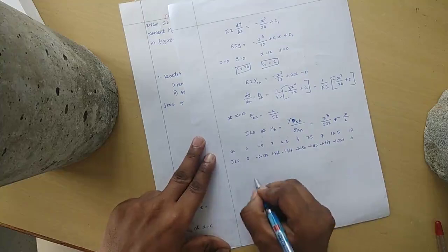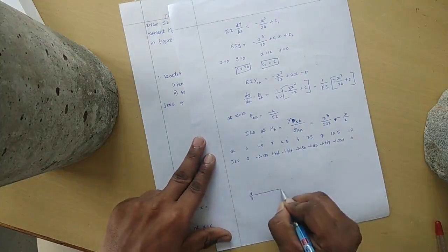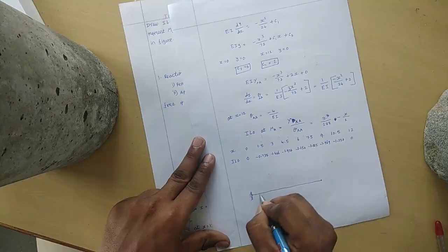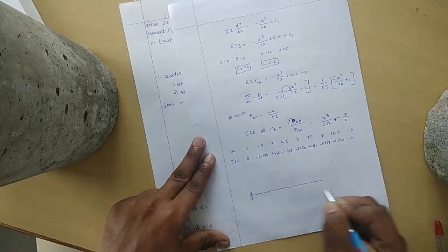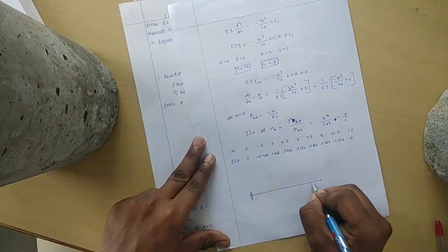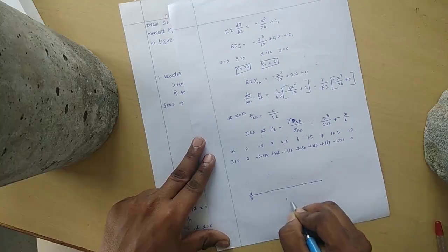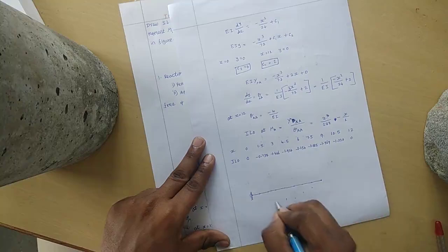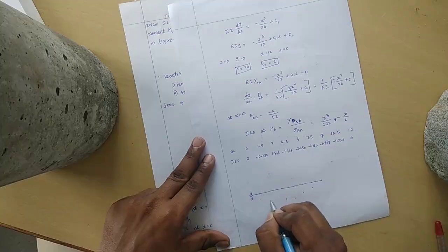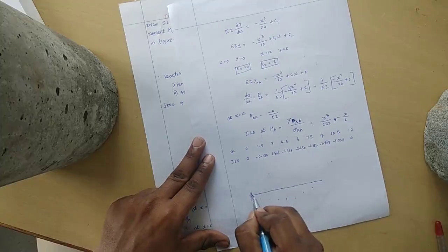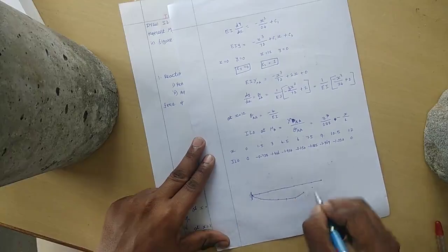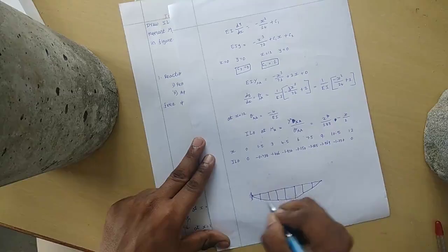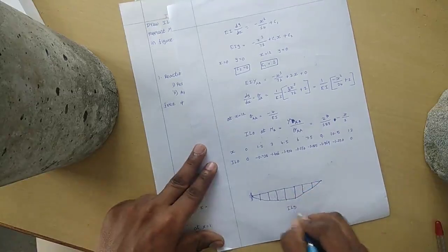Again, we need to draw the influence line diagram. We can say that it is 0 at both the ends. Next, if you mark every point, these are 1.5, 3, 4.5, 6, 7.5, 9, 10.5, 12. At 6 we have the value minus 2.250, next 2.285, next 1.969, 1.230, and it will be 0. On the other side the values will be 0.738, 1.406, 1.934. If you join these, then the diagram will be like this. So this is how you need to draw the influence line diagram for MA. This is the ILD for MA.